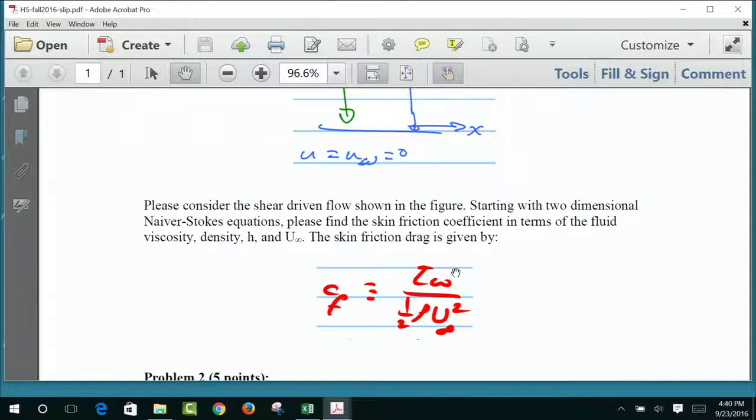So in that case, there will be a velocity profile that's not linear in the pipe. And the partial u, partial y at the center line will be 0. Does this mean that there is no friction? No, because the friction is the partial u, partial y at the wall, not at the center line. Why would partial u, partial y be 0 at the center line for a pressure-driven flow? For a free homework problem, why would partial u, partial y be 0 at the center line?